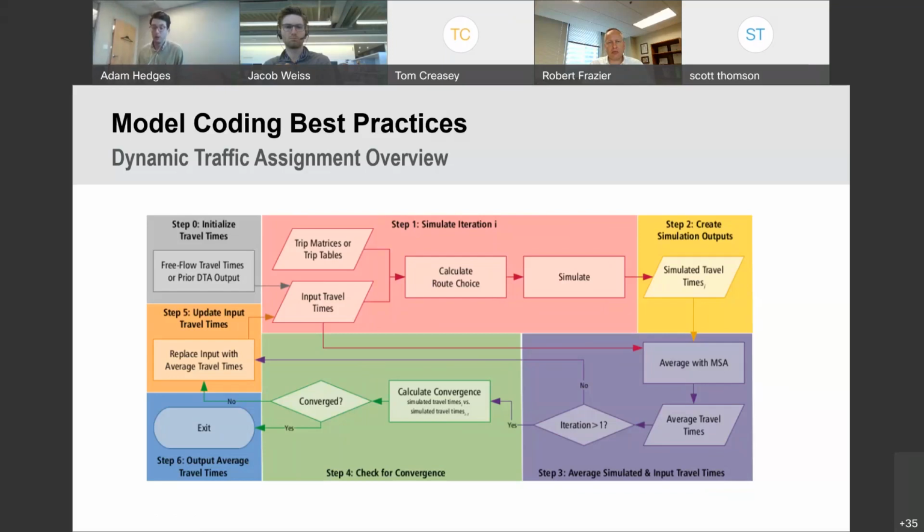And so that was the future scenario. We had the existing scenario, which was just everything's open, typical roadway network. And then they were talking about closing a block for several months and then opening it again with maybe 1 or 2 lanes instead of the full 4 or 5 lanes. And so we're running those different scenarios, and dynamic assignment and using that historic travel time data helped with rerouting people through the network in logical ways.